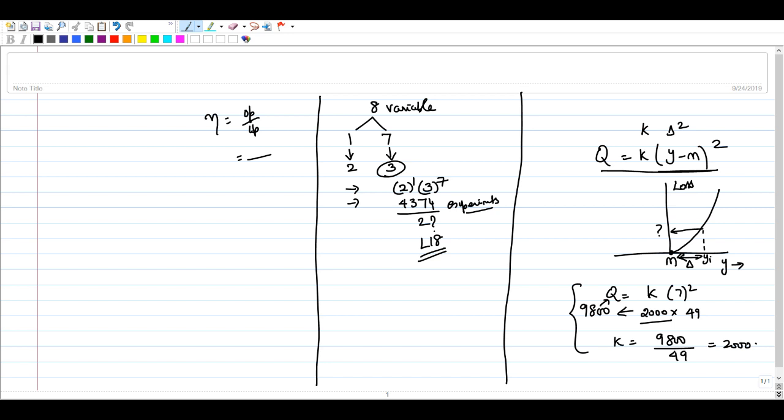Okay, so you apply these three criteria to the part that you are looking at, and if they satisfy all of these three, then that part can be considered as a part that needs to be separated. That's how you identify the theoretical minimum number of parts.